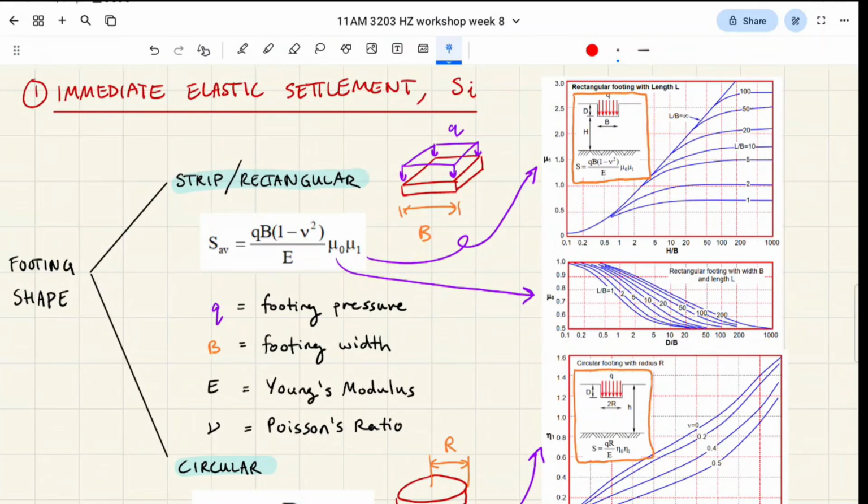So if you have an elastic band, right, the reason it's called an elastic band is as you pull it and let it go, it just returns to its original shape, right? So that's what elastic materials are. They aren't permanently deformed, I guess, right? And that's described by this straight line here. And so the slope of that line is, slope is going to be E, right? That's what elastic modulus is. So the idea is it has a predictable slope, right, for this entire region here.